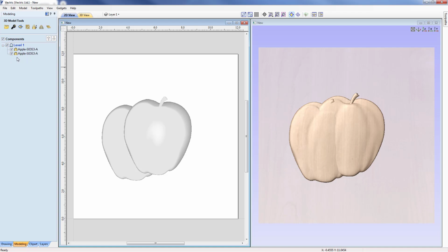With the left mouse key, if we hover over the icon, we'll get information about how it's merging with other models, its base height and the current height for that particular model. So we can see here that the total height is 0.315, its combined mode is merge, and its base height is 0, so it's on the 0 plane. If we move up now to the next model, we can see that we have the same option shown again, and these two items together are merging, and you can see that on the screen where one apple is sort of merging into the other.